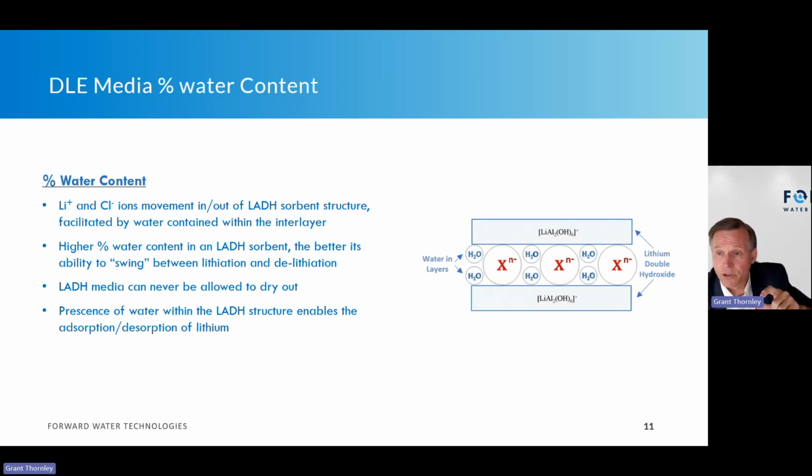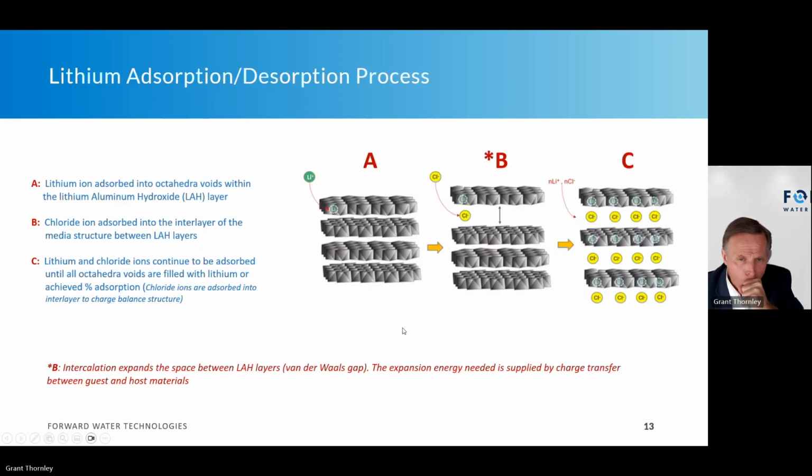It's always covered. It's never allowed to dry out, because if it does dry out, you're not going to recover that media. It's going to be very hard to rehydrate it, meaning get that water back into the crystal form. So take away from this, never let your media dry out, because the water is so important in the transport of lithium and chloride.